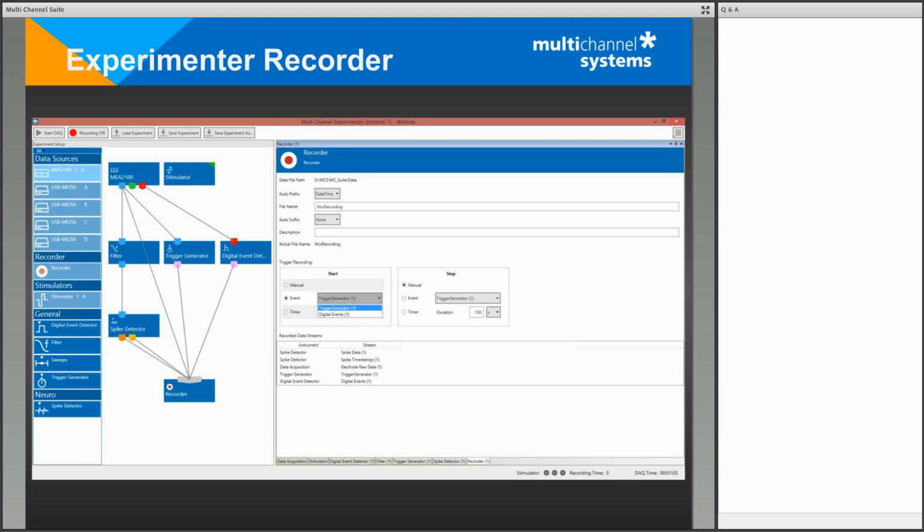And also the general control of data acquisition and recording is very similar. You start data acquisition without recording with this button. When you hit that recording, the software goes into standby mode and then waits for the start command for the recording, which is either starting the data acquisition or some certain trigger. And usually, if the data acquisition is still running and the recording period is at an end, it simply goes back to standby mode and waits for the next event to come.